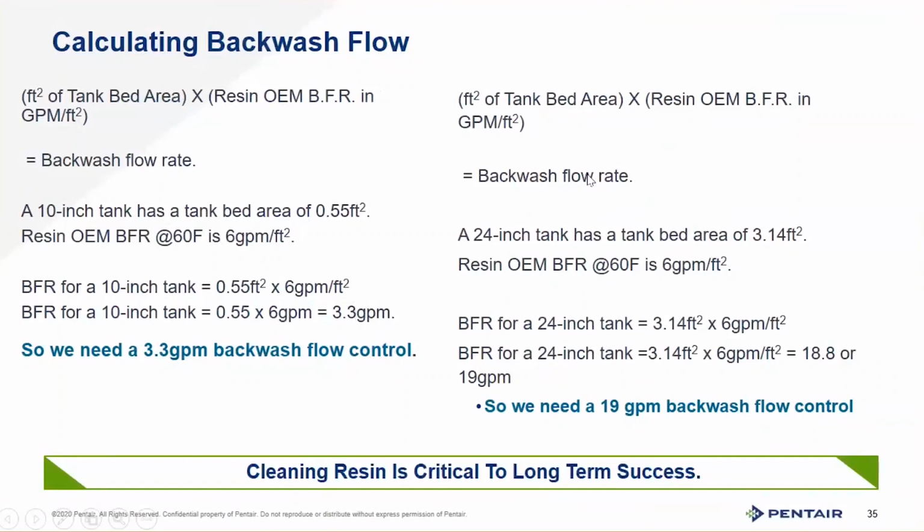Now, in the case of a 10 cubic foot scenario, I need a 24-inch tank to hold that resin. Lots of charts on there on tank size and how much resin they hold. Just go to those charts. You'll pick your tank size off of that. Thank goodness for engineers, they do that math for us.